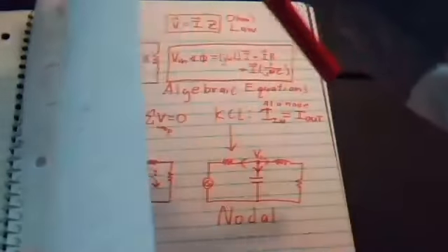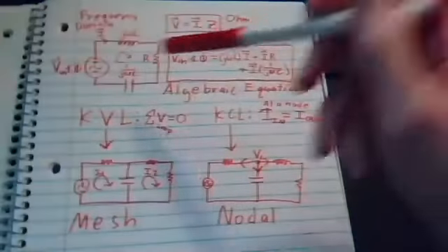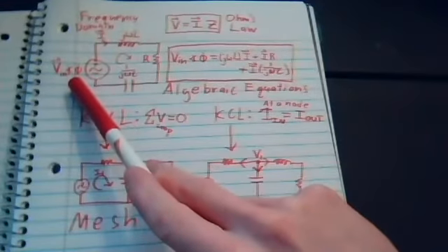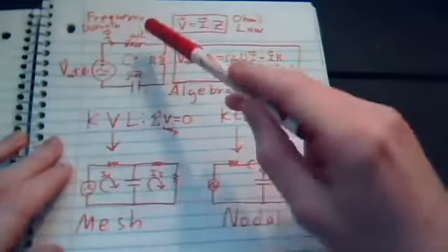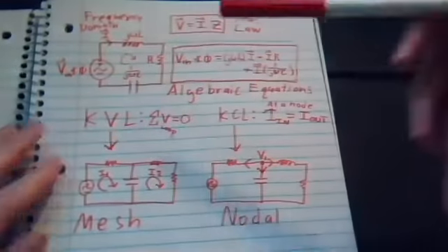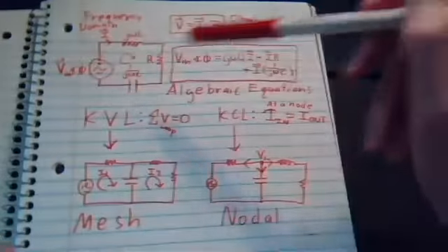If we bring both of those ideas together by pulling the voltage source, or whatever other source you have, into the frequency domain, and we pull all of our components into the frequency domain by converting to impedance, we suddenly have a much simpler situation.